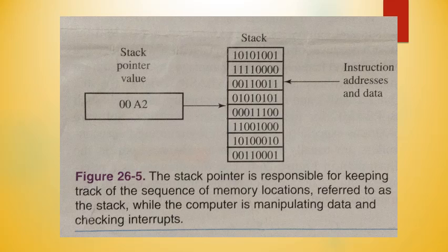An example of a hardware interrupt is when input pin number 3 receives an electrical signal from a push button and the microprocessor stops what it's doing to respond to the signal. While it is responding to the push button signal, a hardware interrupt, the contents of the program counter are pushed onto the stack. The stack pointer bookmarks the location of the last item pushed onto the stack. When the processor finishes servicing the interrupt, the computer address is popped from the stack and returned to the program counter, and the microprocessor continues processing the instructions in order.